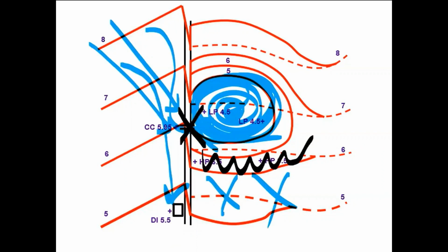These two different systems, one where you have a raised drop inlet in the bioretention system, and the other where you have no raised drop inlet, but you have a drop inlet in the parking lot, are the core of what you're going to be doing for these systems. And again, getting the elevations correct is what makes this work, and we'll be talking about this a lot more.